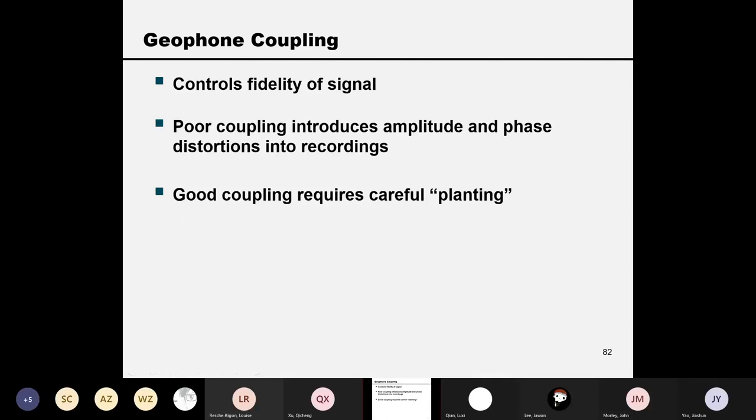That was the mechanism of the geophone, but in the acquisition in the field, one important thing is called coupling. Okay, when I started as a geophysicist, I worked in the field, so my job was to walk around, over a distance of 10 kilometers or so, and plant your geophone into the soil, okay? That's quite a tedious job, but really important for the fidelity of your data. You cannot simply use a foot to punch that. No, that will damage your geophone, okay?